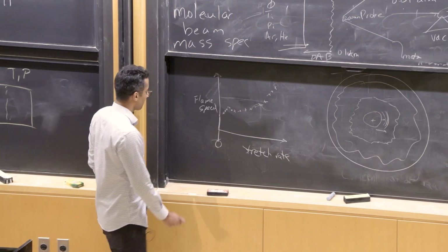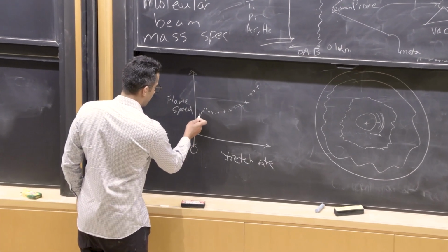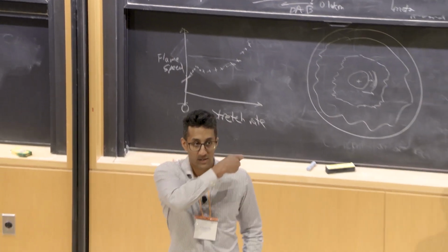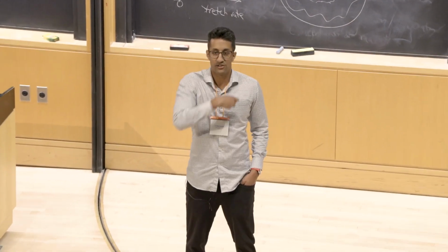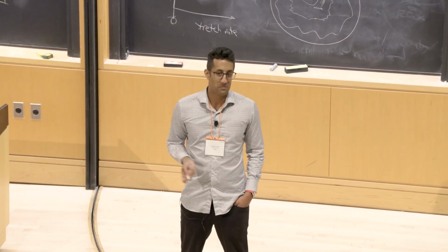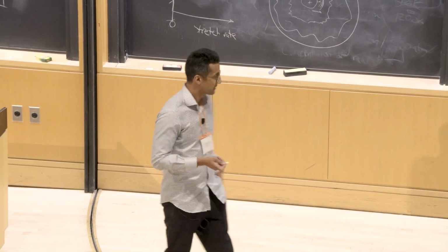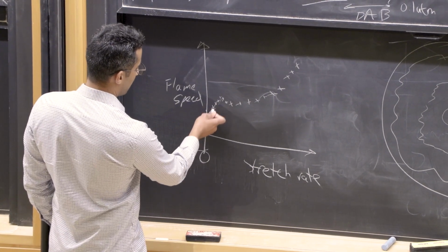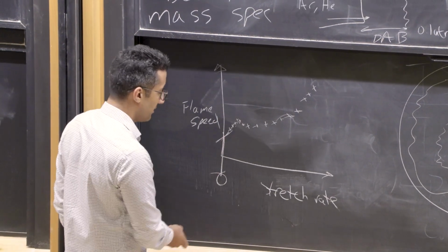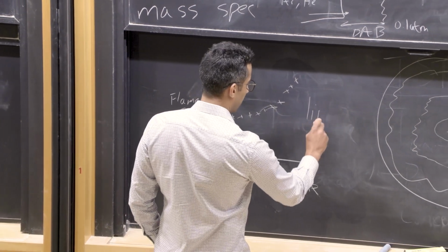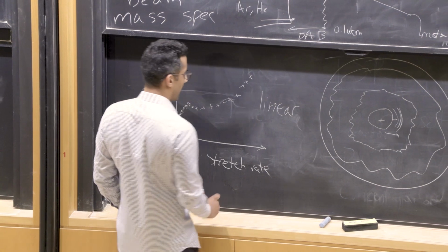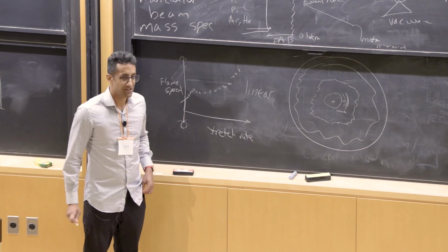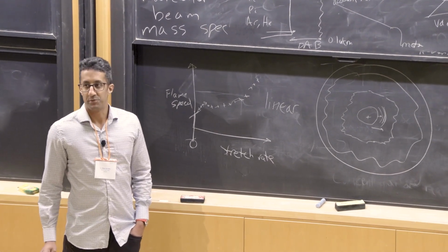right? So they always try to find some fitting of where the flame speed crosses the y-axis, or the x-axis at zero stretch. And that has to be done using some mathematical correlation, yeah? They basically take the points just before zero stretch, the nearest points they can measure, and they fit a line, and sometimes they just make a linear correlation. For many years people fit a linear correlation, and they extrapolate to zero stretch, and they said, this is the flame speed at zero stretch.